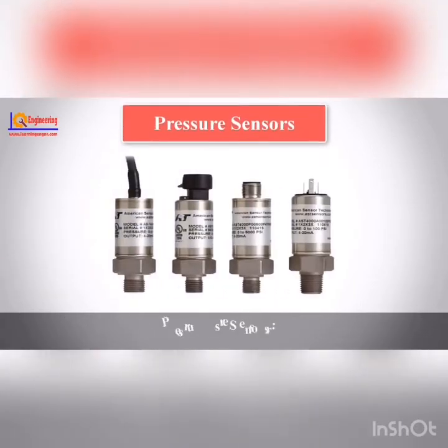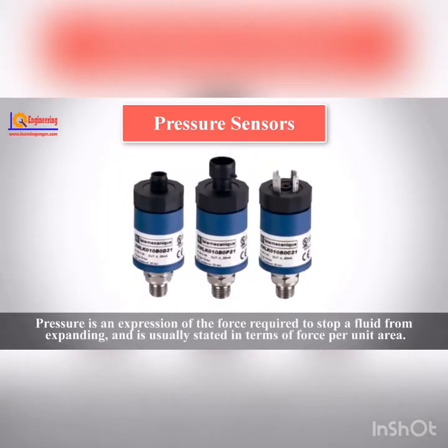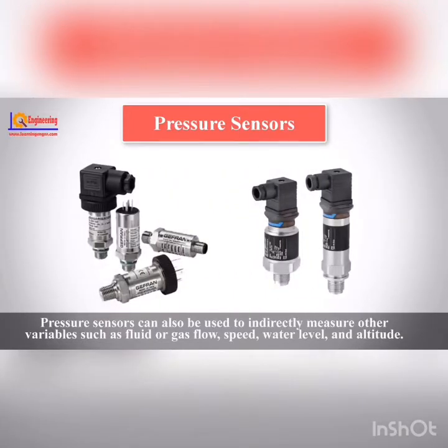Pressure sensors. A pressure sensor is a device for pressure measurement of gases or liquids. Pressure is an expression of the force required to stop a fluid from expanding and is usually stated in terms of force per unit area. A pressure sensor usually acts as a transducer. It generates a signal as a function of the pressure imposed. Pressure sensors can also be used to indirectly measure other variables such as fluid or gas flow, speed, water level, and altitude.